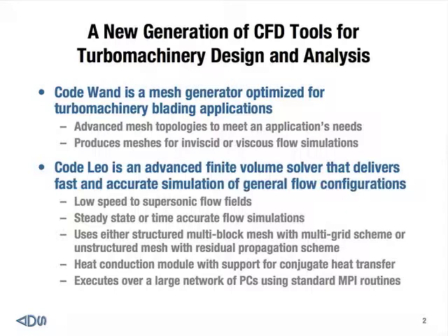And since, as I mentioned, the code can do both structured and unstructured mesh, that makes this code very versatile for many, many applications. We also captured the best qualities of those meshes. For structured mesh, we are using the conventional multi-grid scheme to accelerate convergence. For unstructured mesh, we also have something called a residual propagation scheme to help the solution converge faster to the steady state you're looking for.